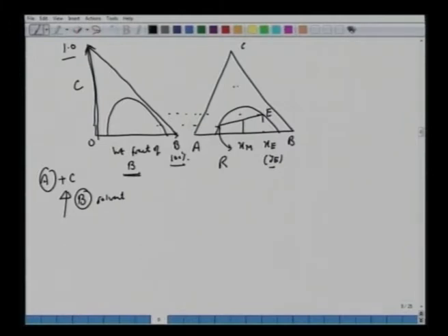Of course, here if we choose any coordinate, we can read all the 3 readings. But the most important is what is the amount of contaminant solute you have in the system and how much solvent you are adding to remove this. So generally on the x-axis you plot weight fraction of B, and here you plot weight fraction of C. A would be 1 minus B and C anywhere. So we don't need to plot exactly on this equilibrium triangle.